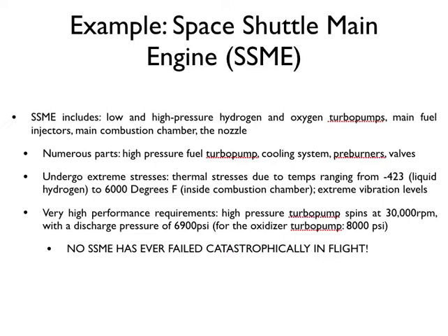So the SSME includes a variety of different subsystems. It has low and high pressure hydrogen and oxygen turbo pumps. It has main fuel injectors, a main combustion chamber, and a nozzle. And again, I'll show an example here in just a second.